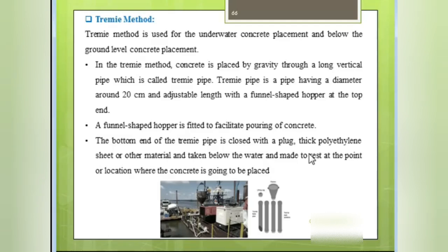Generally, this funnel method is used for pile construction, where the site is very muddy or has a sandy surface underground. Where we require concrete piles, first with the help of a drilling machine, drilling is done into the ground, and after reinforcement, concreting is done through the funnel. Okay, so that is called the tremie method.